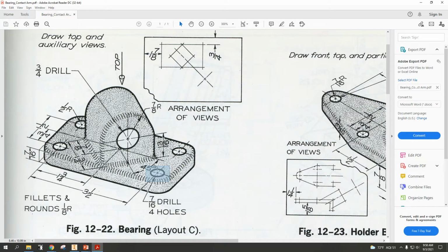And I'm thinking about that because I could leave the centers and try to access or show those holes later, which could have benefits. If I use the hole feature, that might work out better down the road as you get more experience. If I put the circles in, when I extrude, I'll extrude the holes in rather than extrude it solid and then have to cut the holes.